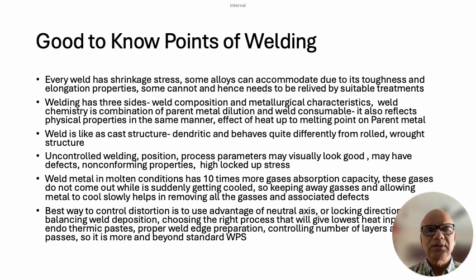Weld, as we said, is a cast structure. It's a dendritic structure and behaves much differently than the rolled structures. So we must understand the as-welded properties of the alloy and the selected consumables. Uncontrolled welding position and process parameters may give a uniform visual look, but will surely have different percentages of non-conformances, defects, or locked-up stresses.